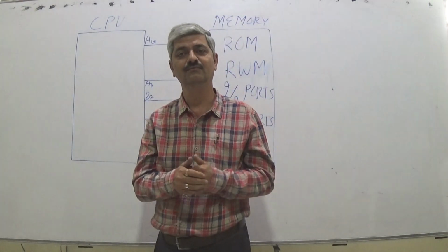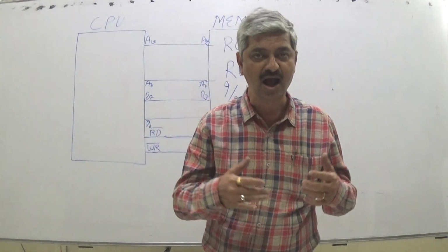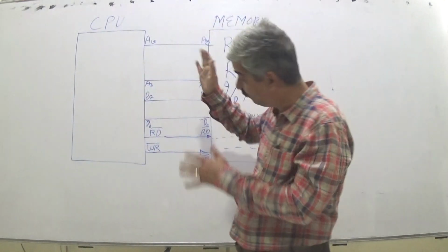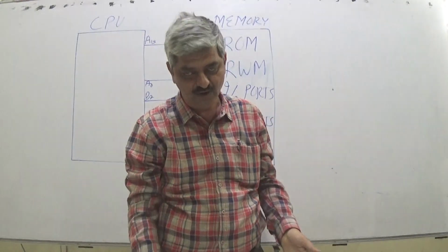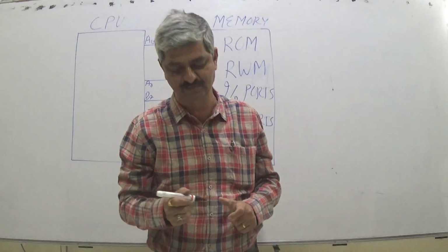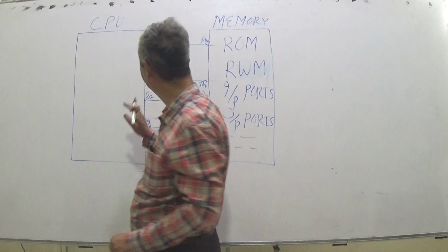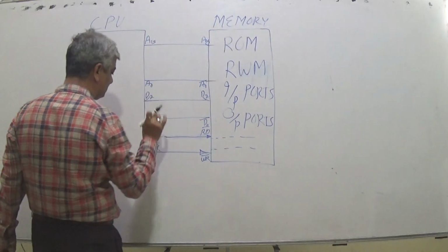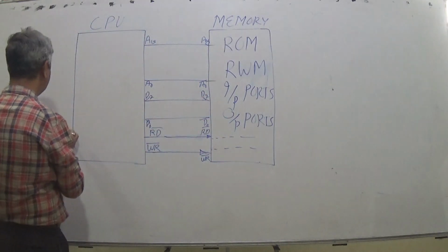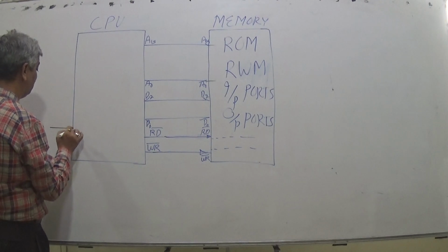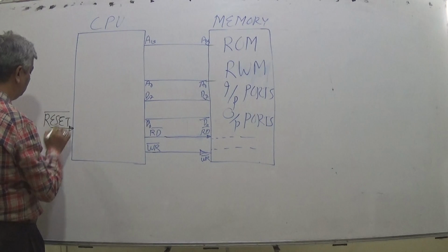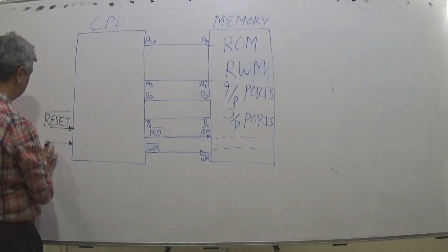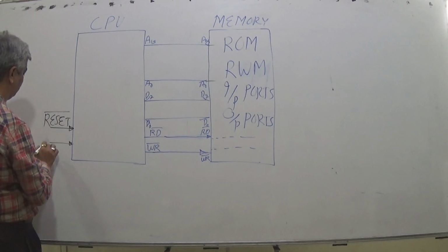Now we proceed. A big picture is created of the microprocessor based system: 16 address lines, 8 data lines, 1 read bar, 1 write bar. As stated, the microprocessor has 1 reset bar and 1 clock pin. The activities are sequenced on the clock.